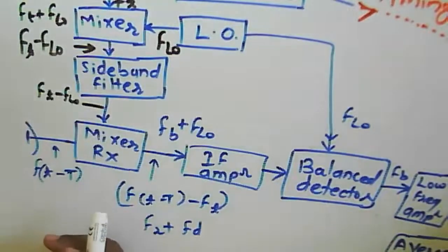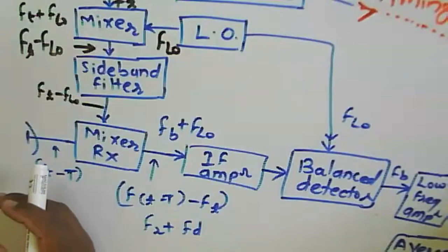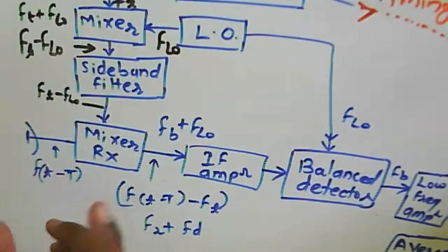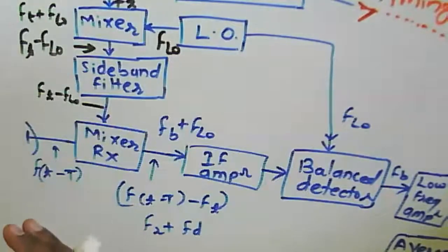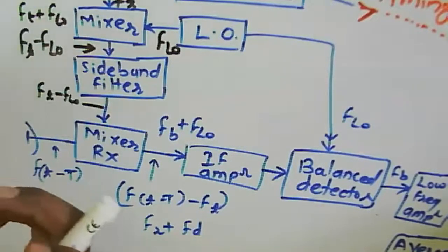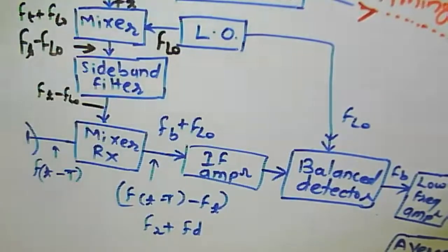So in that case we are supposed to get a weak signal, and that weak signal is supposed to be considered part of the noise. If the range is small, we should get a high level, strong signal. But if we are getting a small signal level in that particular range, it is considered noise at the receiver from some other object, because we consider that the range is small.